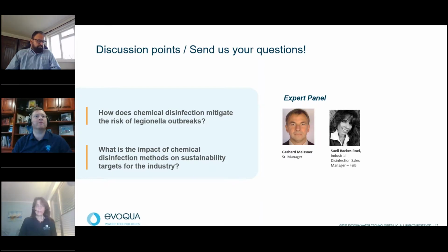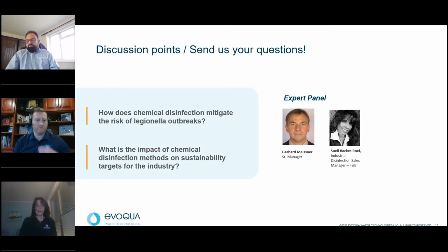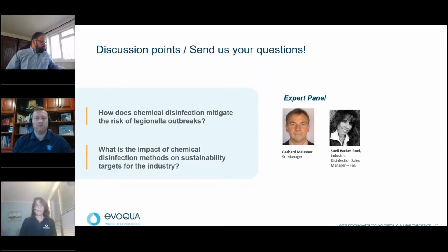When you add chlorine dioxide, you need to be aware of two things. The one thing is the excess of acid that is in the chlorine dioxide solution. The other thing is that chlorine dioxide also oxidizes iron. So iron 2 and iron 3 is getting oxidized by chlorine dioxide, which then precipitates to iron hydroxide.